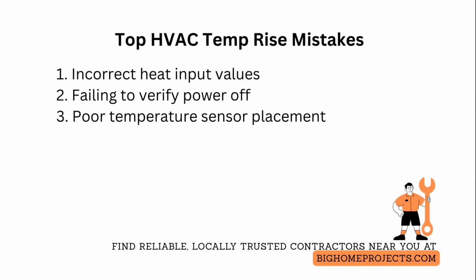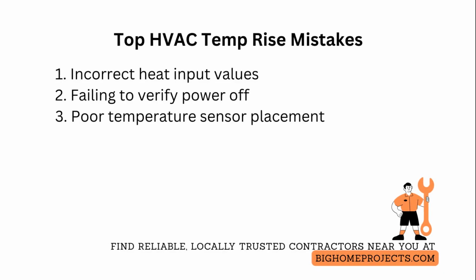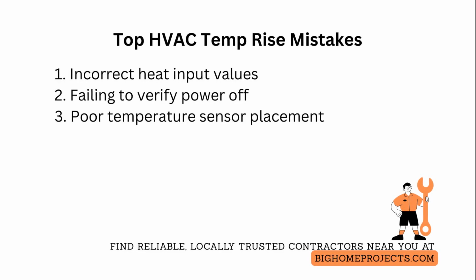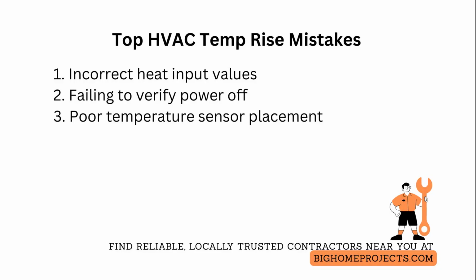One of the next frequent issues is failing to verify power off before setup, leading to electrical hazard and damaged instruments when measuring temps or opening compartments. Fix by switching off the breaker, testing for voltage with a properly rated multimeter at the service disconnect, and confirming no voltage present at the terminal block before touching wiring.